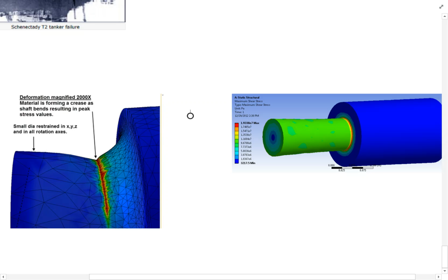So in this shaft, and in this portion of the shaft, I'll mesh fairly large, so the thing will compute quickly. But in this area here with the radius, as you can see here and here, I've tightened my mesh up significantly. So I've selectively reduced my mesh so I can pick up that stress concentration. If I didn't do that, I might not even see that. It might show blue fading into green, and I wouldn't get the stress concentrator that I see there. Okay.